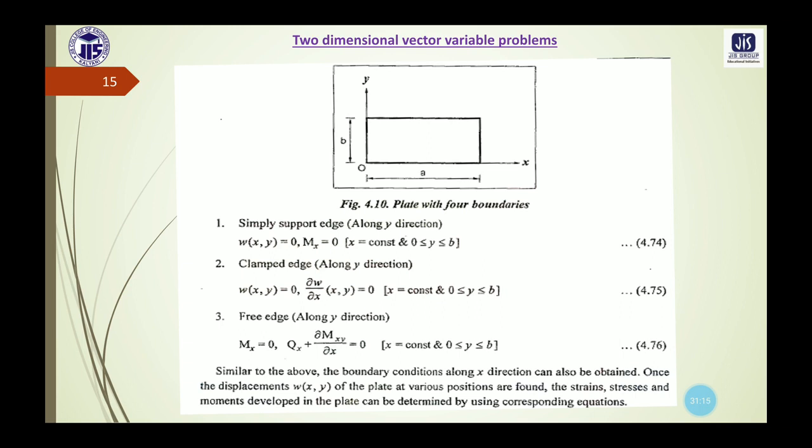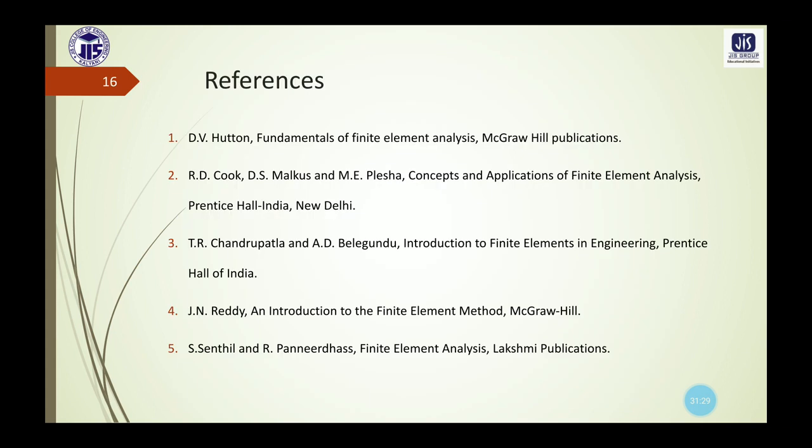Now similar to the above, the boundary conditions along the x direction can also be obtained, and once the displacement w(x,y) of the plate at various positions is found, then the strains, stresses and the moments developed in the plate can be determined by using the corresponding equations.